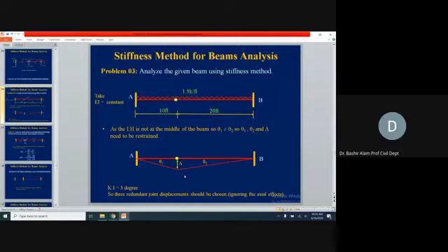Now I don't want to put these thetas and deltas. I would straight away go by these notations now. So you draw this sketch quickly now. Show the internal hinge, fixed ends now, and throughout it is loaded with 1.5 kip per foot. It's a very interesting problem, and we will solve this quickly now. It is a 3 degrees indeterminate problem. These 3 degrees I'll be showing you in the next slide now.